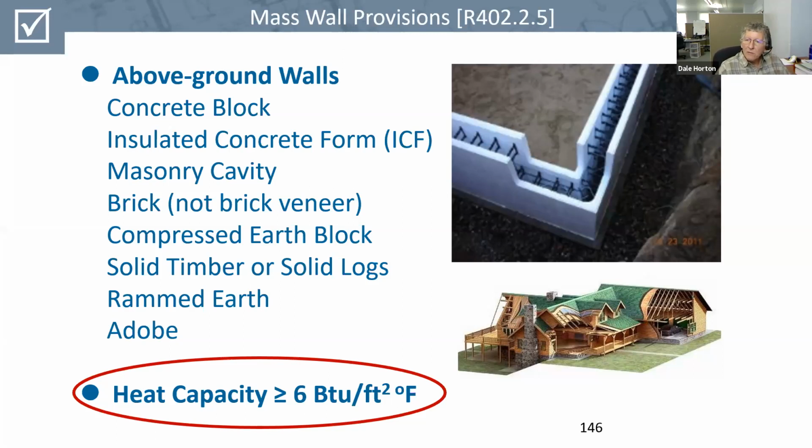Carl, you mentioned a couple questions. Is the R value for stick frame cathedral ceiling still R38 with the 2018 code? Well, it's going to be the same as the current code. The way I'd explain it is it's R38 if it's continuous, it has R38 value all the way over to the exterior wall, and R49 if it does not. So regardless of whether it's a cathedral or attic, the insulation requirement allowables are the same, with the exception of that one 250 square feet where you can have a lower R value. But the R value requirements have not changed. Was there a second question, Carl?